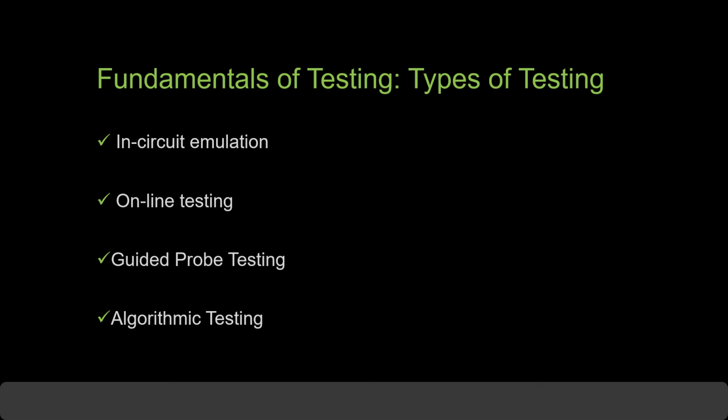Then we have algorithmic testing, which refers to generation of the input patterns during testing. Counters and feedback shift registers are typical examples of hardware used to generate input stimuli. Algorithmic pattern generation is a capability of some testers to produce combinations of several fixed patterns. The desired combination is determined by a control program written in a tester-oriented language.